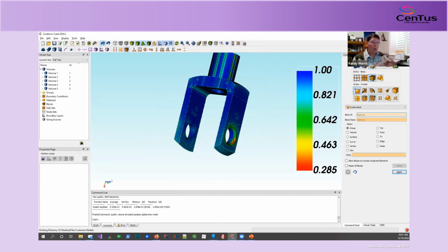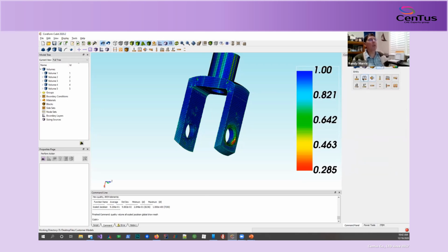All of these steps are relatively straightforward, and some codes will accept those boundary conditions, blocks, side sets, and node sets. The boundary conditions associated with them, we can set up, force and pressure and heat flux and temperature, a bunch of CFD boundary conditions. Some codes just have you export the mesh directly into them and set up all the boundary conditions there. So that's a typical scenario at Sandia, where they set up the boundary conditions in their simulation codes.